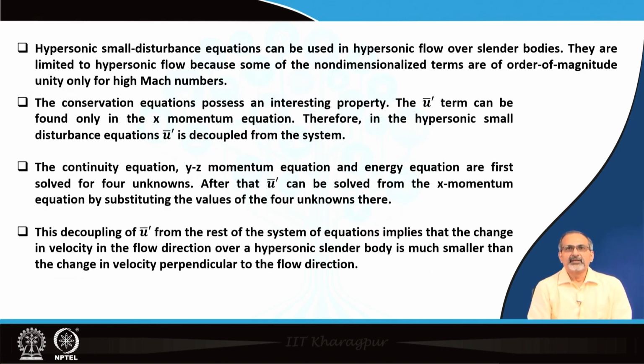To discuss a little bit about the nature of these equations and the consequent implications, hypersonic small disturbance equations can be used in hypersonic flow over slender bodies, like we had shown in that sketch. They are limited to hypersonic flow because some of the non-dimensionalized terms are of order of magnitude unity only for high Mach numbers.